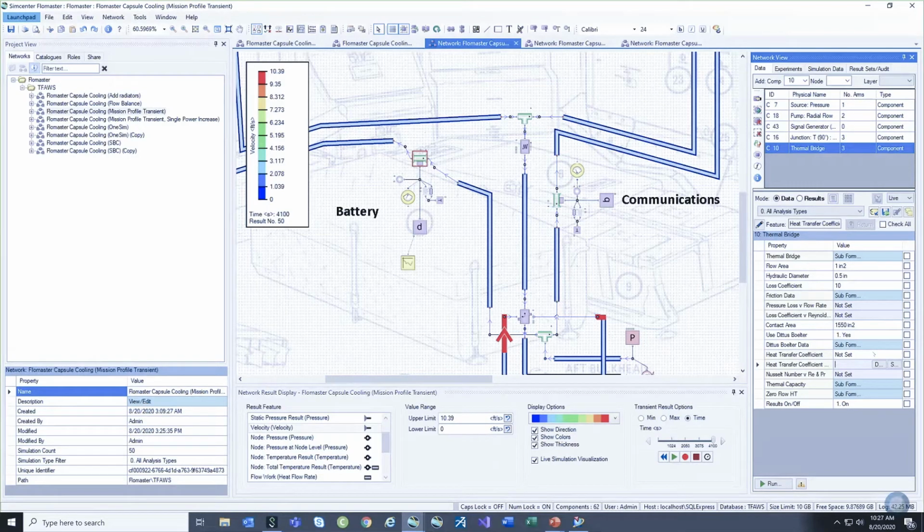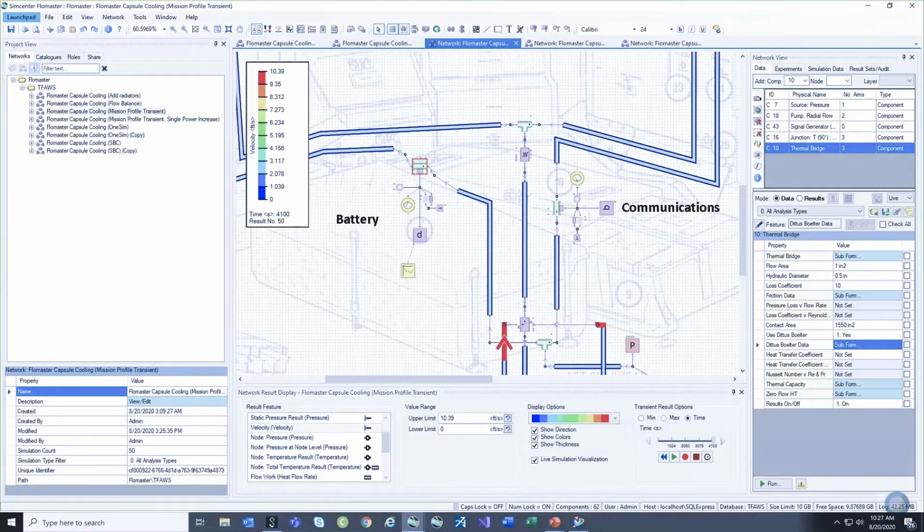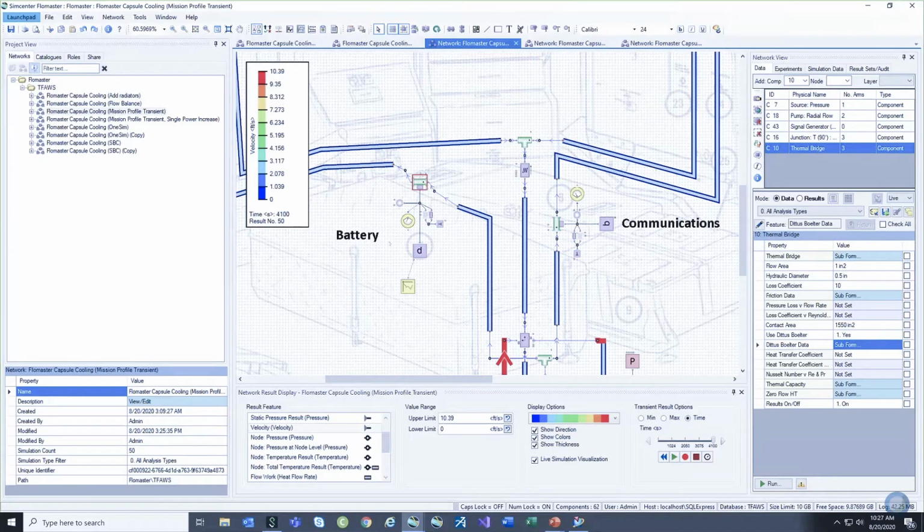So what would we do to capture that additional physics? We could come up with just a wild guess for the heat transfer coefficient. We could look it up in a textbook. We could use engineering know-how. We could do a bench analysis, right? So we could go to a lab, take our cold plate, add some instrumentation, run some flow through it, and define our heat transfer behavior. We could go to the vendor and ask them for it. Or we could use 3D CFD to determine that.